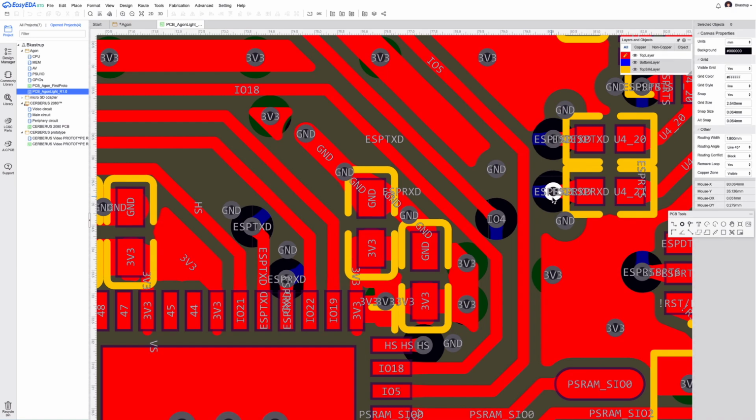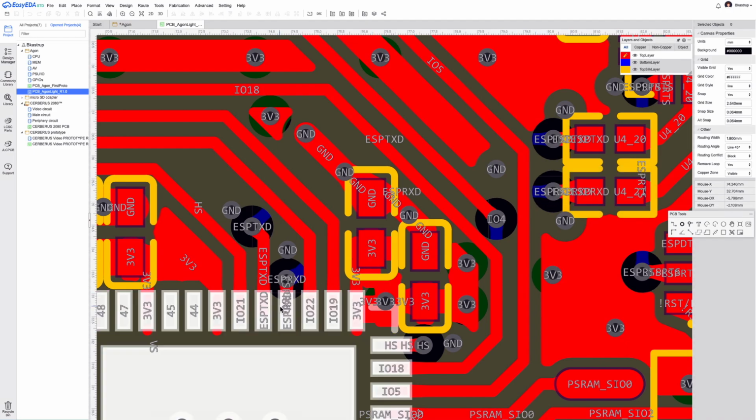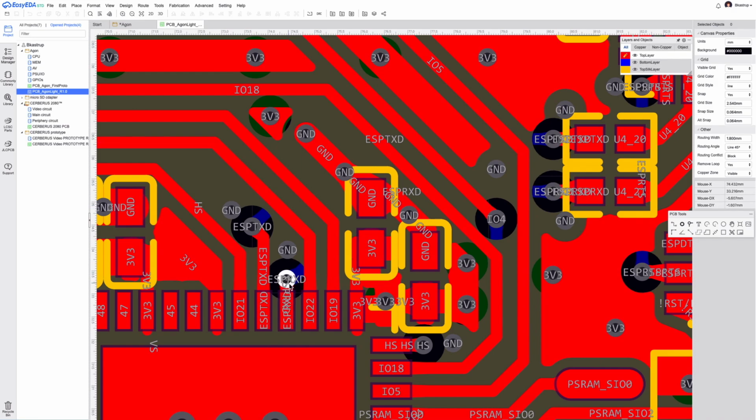I don't have time to explain in one video what exactly this is. There's a lot of theory involved, but the point is the following. Every time a signal goes from a driver to a receiver, like in this case it goes from this driver resistor here to the ESP32, current has to return from the receiver back to the ground. Every electrical signal is a closed loop. If you don't provide a return path ground via, so the current can return through this via, the circuit will find a return path somewhere. And what will happen is that the return current will spread itself around a large part of the board, looking for the lowest impedance return path that is available. And it will always find something.